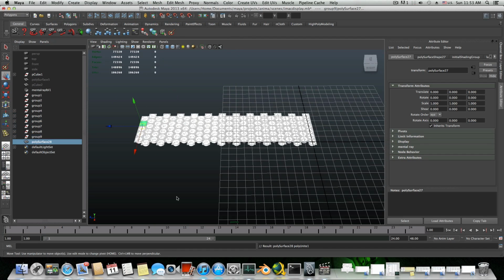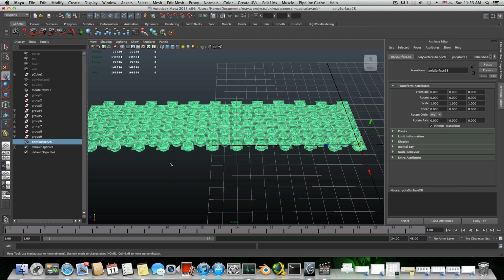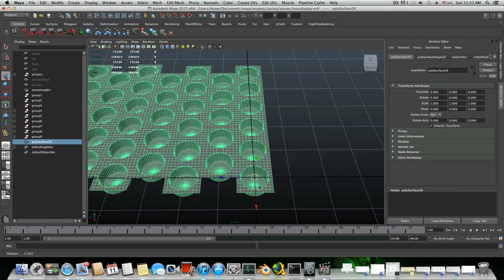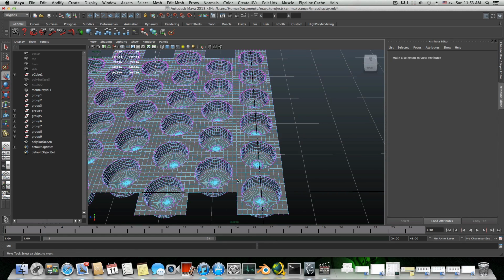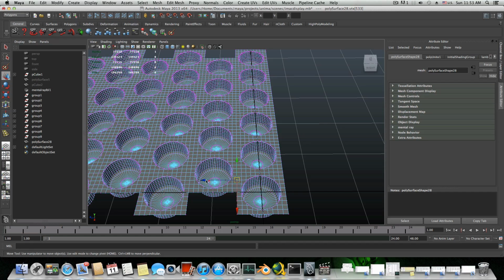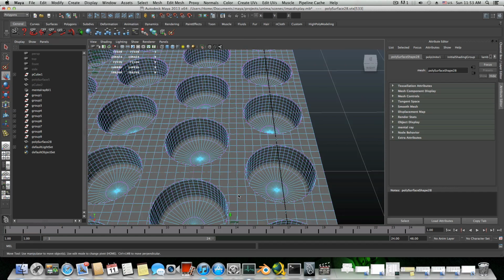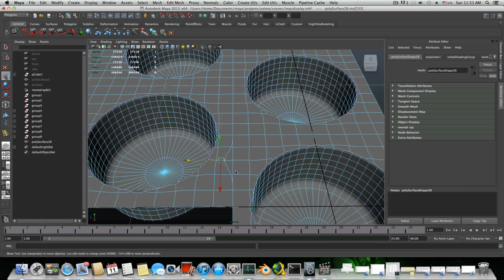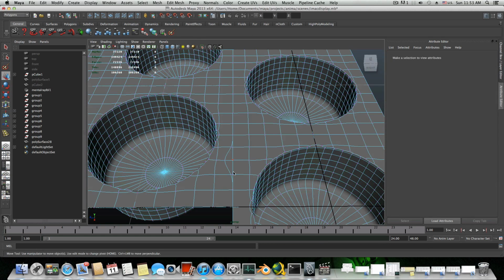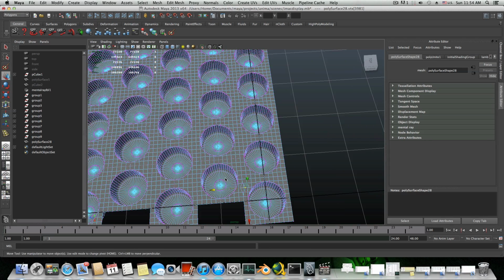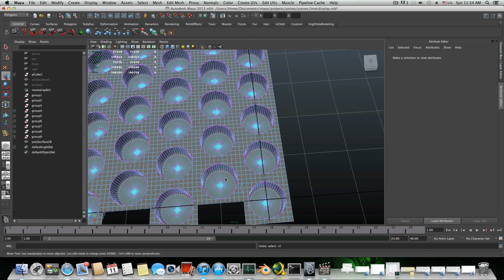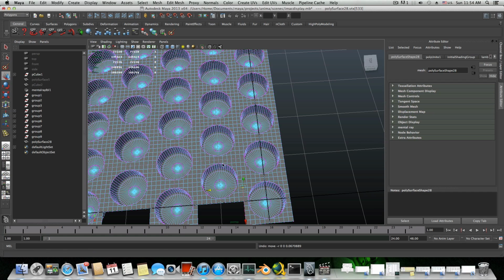Okay, mesh combine, and we will have to wait a second because Maya is becoming very heavy right now, and now it's one piece. Now it's not one piece because we still have not connected most of the vertices in the middle where we attach those pieces. So let me just show you. If I will move this, you may see double sides, or open gaps, I'm not sure. Control Z. So maybe you don't see nothing and it's all for good.